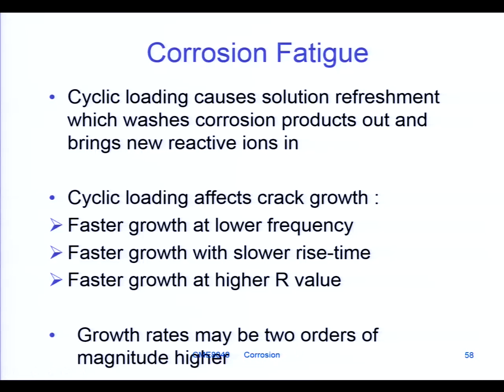For cracks to develop, you need some initiation points, some stress concentration. And that quite often in a corrosive environment is where there's a pit formed.